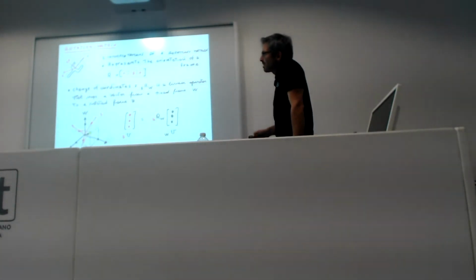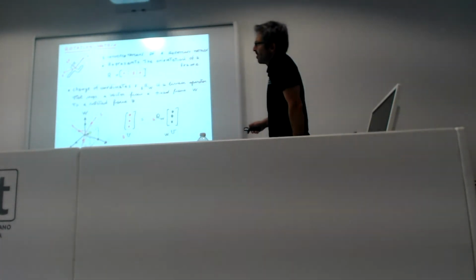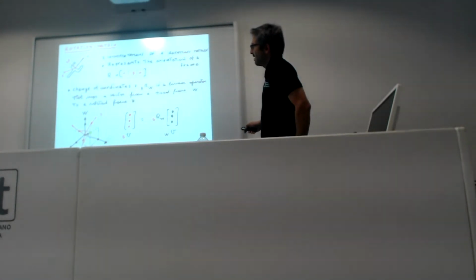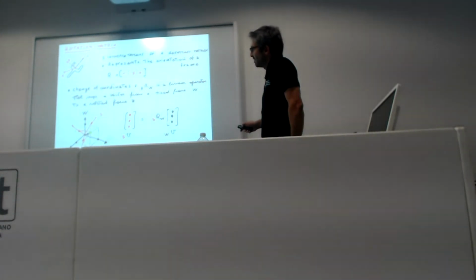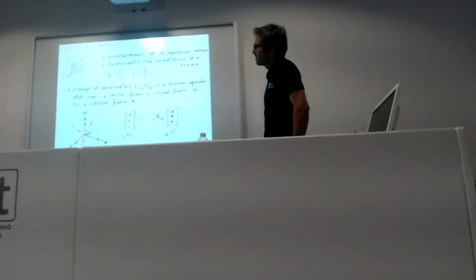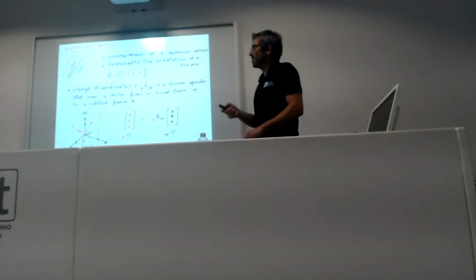If you look at this, you have the vector V here in green that has its components in the world frame, and then you have the base frame, the red one, rotated, and the rotation matrix just maps this vector into the base frame. So the outcome are these 3 numbers that are the coordinates of the vector V in the base frame.